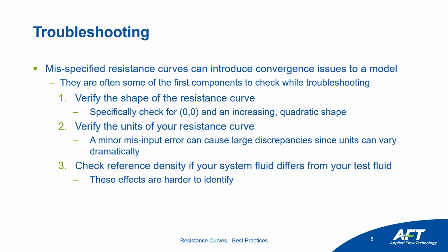Third, check the reference density if your system fluid is different from your test fluid. Not to belabor the point any further, again, we can see that discrepancy where at the same head loss, we should expect different pressure losses for different fluids.